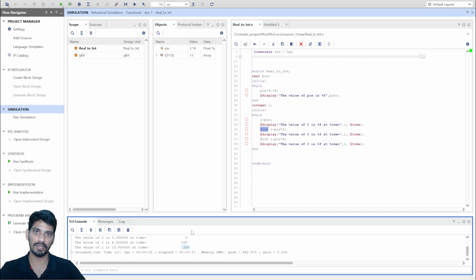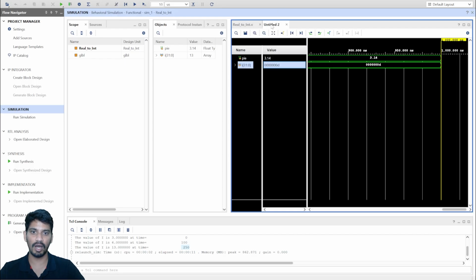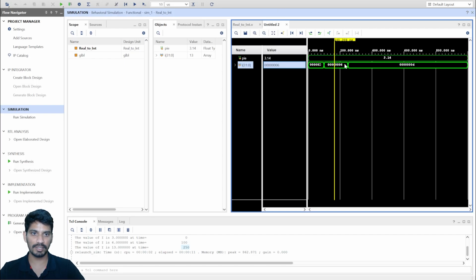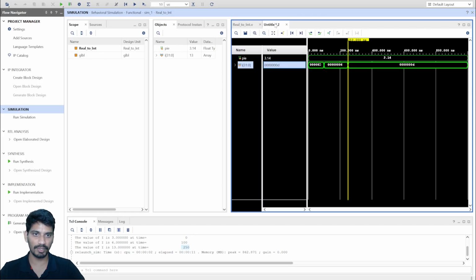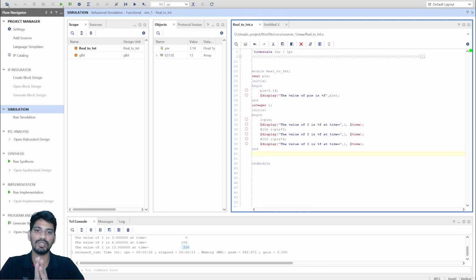This is very, very important. This shows that the flow is not concurrent but sequential in Verilog in our initial block. You can see the same thing here. At 100 nanoseconds, the value is 6. After, not 200, we have added 100 plus 150, so after 250 nanoseconds, it went to value 13, which is represented by D. So this is the use of the time keyword.